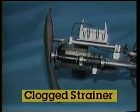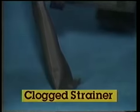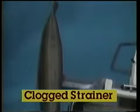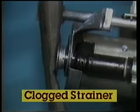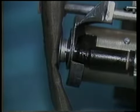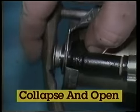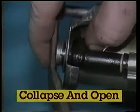A clogged tank strainer could cause an engine to stall erratically. If partially clogged, the strainer can occasionally collapse and stop all fuel flow to the engine. This problem will not show up during a pressure test unless the strainer is still collapsed. You would have to measure pressure as soon as the engine stalls. If still collapsed, your pressure readings would be very low.